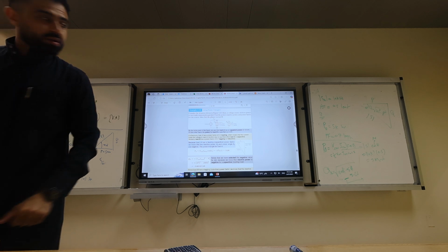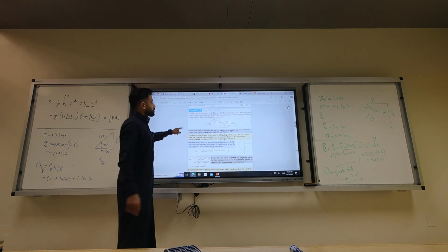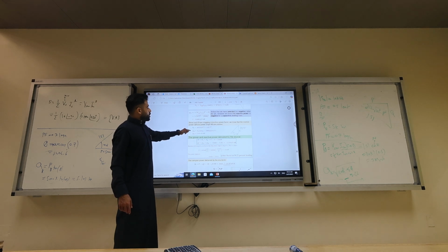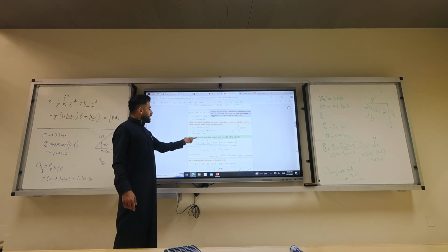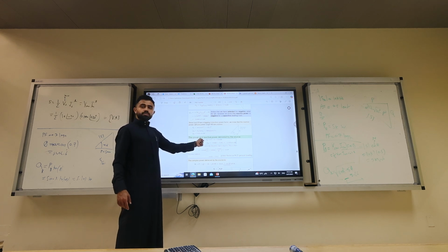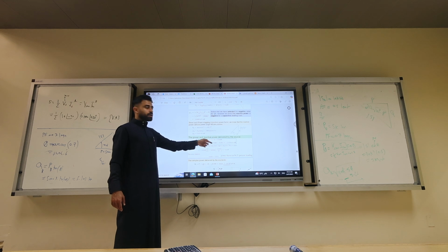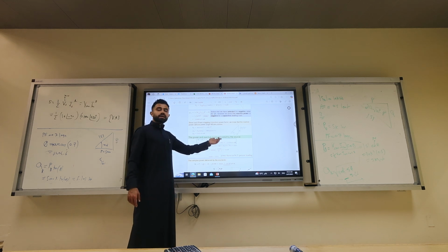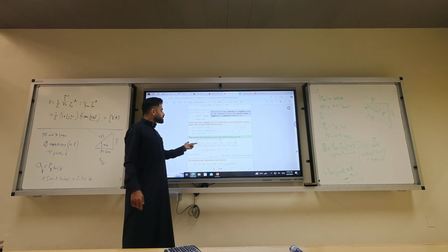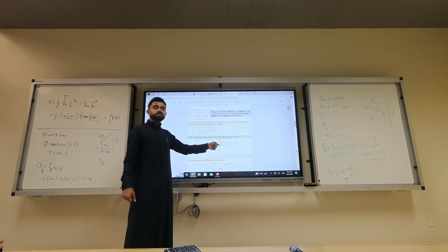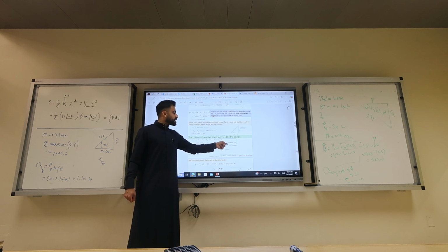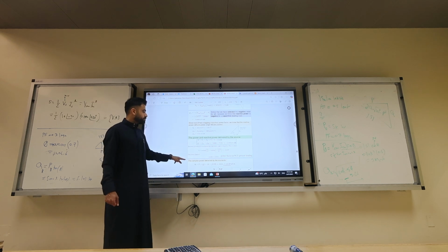Now, I know QB, PB, PA, QA. So I sum PA and PB, which is 5 plus 5, which is 10 kilowatts. And this is for the source. The source is delivering 10 kilowatts. And it's delivering the Q, which is minus 8.66 for the A, plus 5.101 for the B, which is minus 3.559 kilovars by the source.